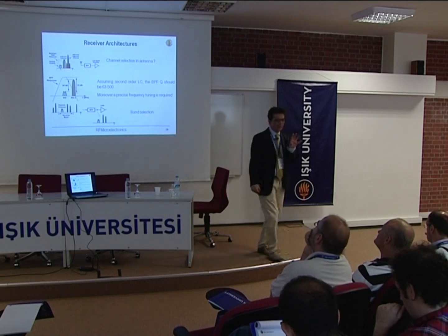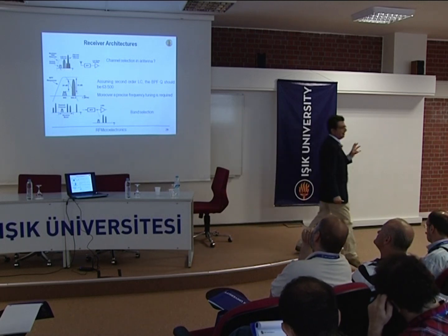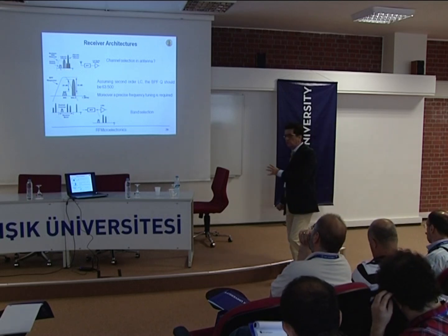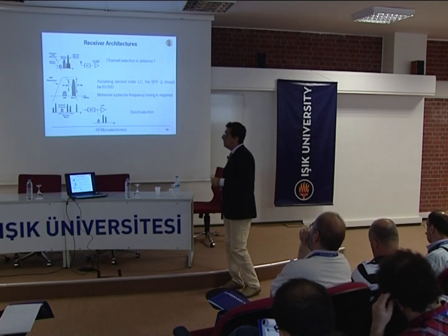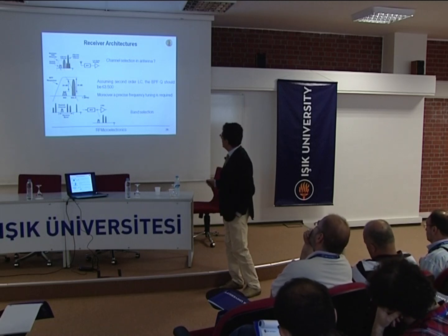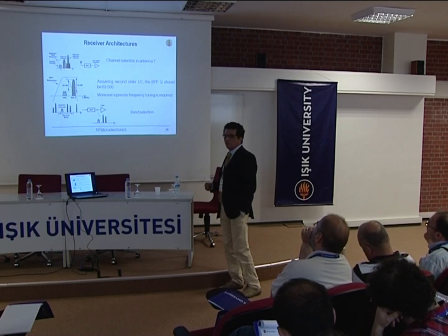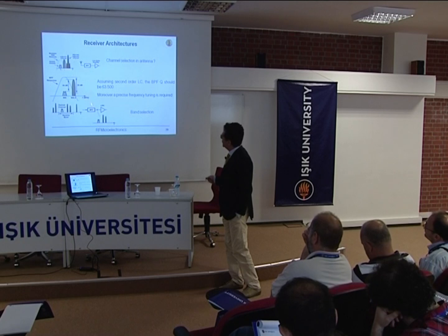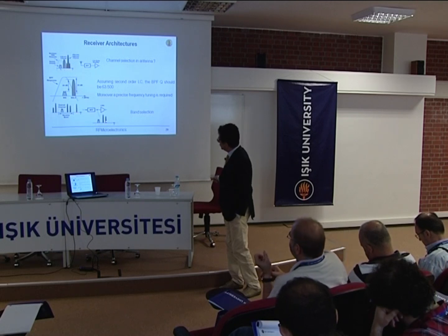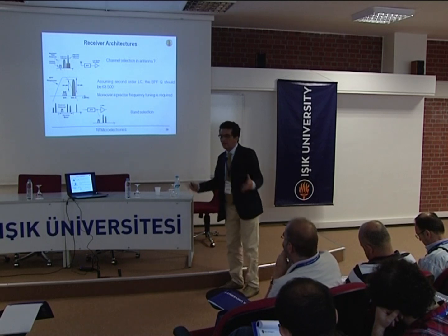Anyway, this gives you a clear idea of why you cannot think about selecting a channel and down converting, and digitizing it before making any other kind of operation. So the only thing that we can think about is band selection, which means that somehow we can use a bandpass in between the antenna and the receiver and throw away the interferers outside the band of application, so still keep everything which is in a given bandwidth.